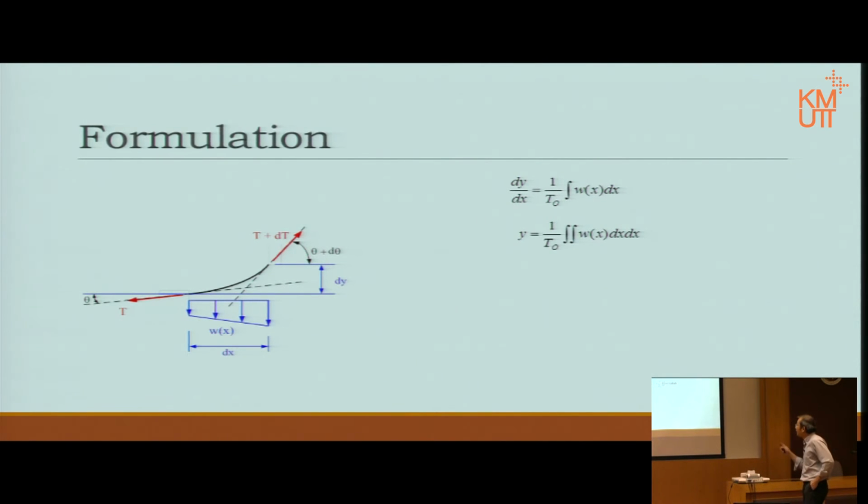Okay, that expression apparently represents the relationship between x and y coordinate of every single point on the cable. Okay, because that x and y is measured on the point of the cable. Okay, now, if we know the geometry, then we can cut free body diagram at any point, and of course we should be able to know the angle, because if we know xy coordinate, then we can differentiate for the theta, right? And then we can calculate every single point on that cable.